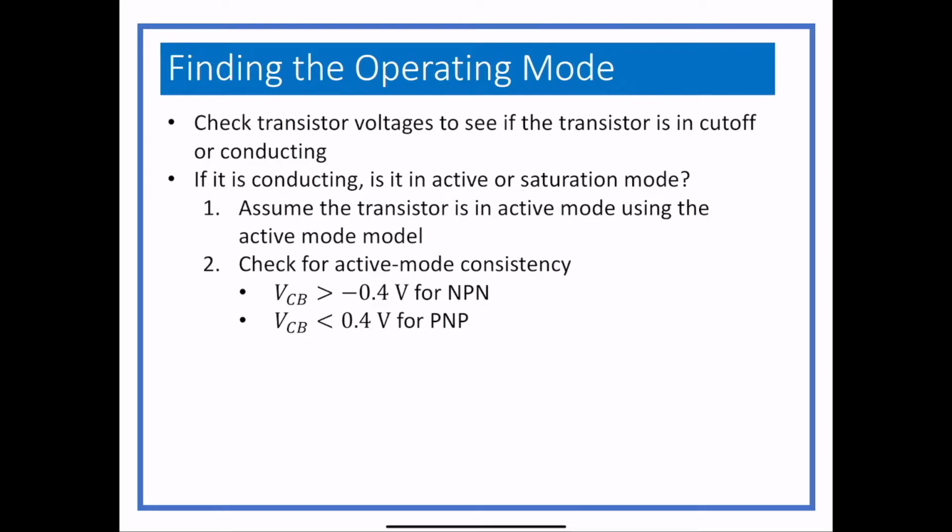For instance, if you have a VCC of 15 volts and you go ahead and you find a base current and that's all good, and you find your collector current and that's all good, and then you try to find, say, the voltage at the collector, you take VCC and you subtract IC times RC, and you get a negative number, which won't happen in a circuit where you have positive 15 and 0.